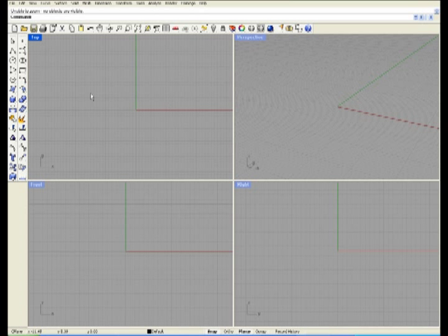So the first thing we're going to do is select box. On the left part on that toolbox, we're going to select box, and we're going to leave it pressed, and we're going to choose a cylinder. Now, before you draw anything on the grid, you should go to the bottom part.